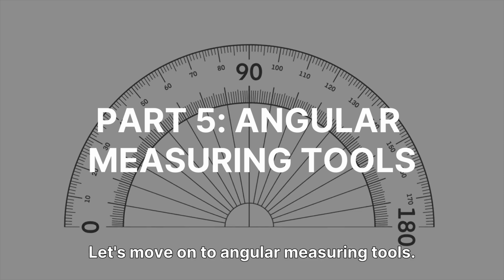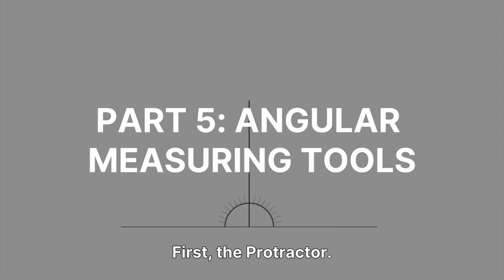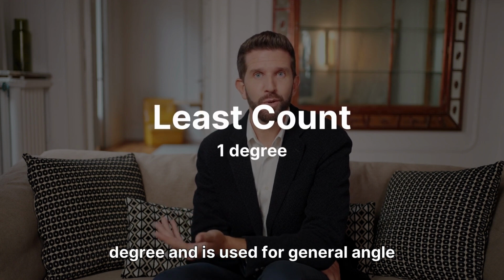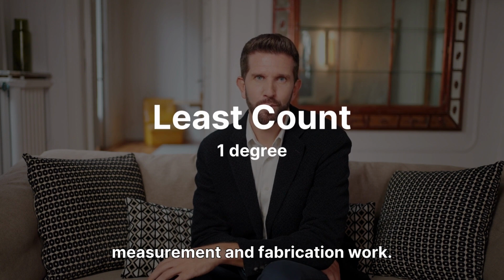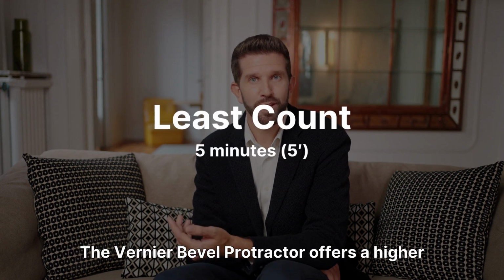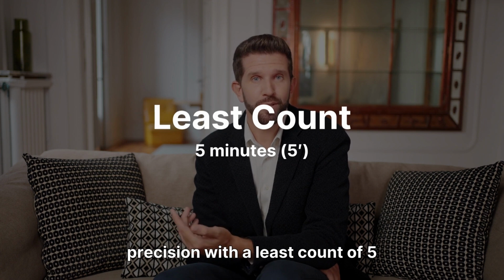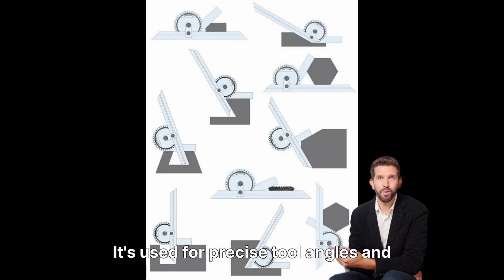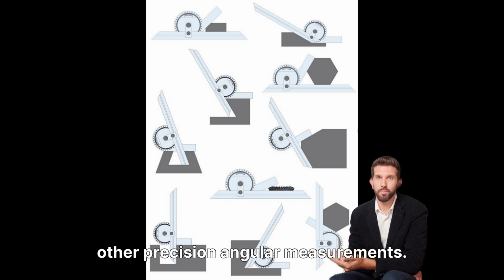Let's move on to angular measuring tools. First, the protractor. It has a least count of 1 degree and is used for general angle measurement and fabrication work. The Vernier Bevel protractor offers a higher precision with a least count of 5 minutes. It's used for precise tool angles and other precision angular measurements.